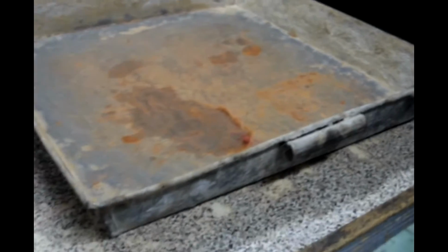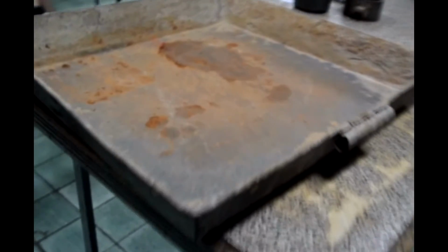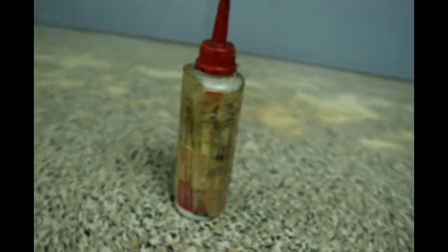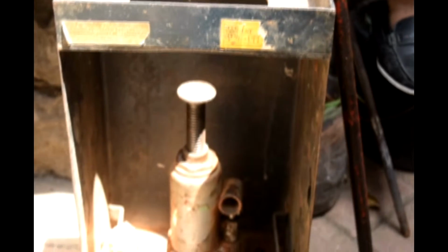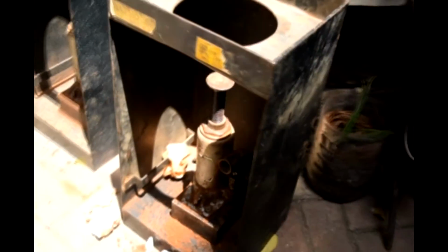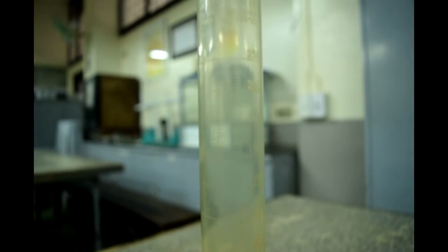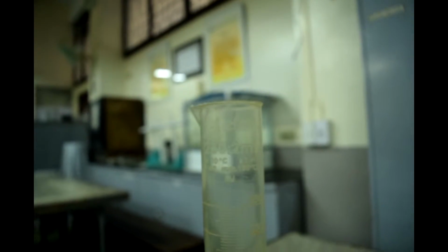Mixing pans. These are used to contain huge amounts of soil and water for mixing. Trowel or shovel. It is used to assist in mixing the soil after water is added. Oil. The oil will be applied in the mold and collar so that the soil will not stick to them. Mechanical extruder. This consists of a hydraulic jack that will be used to remove the compacted soil from the mold.